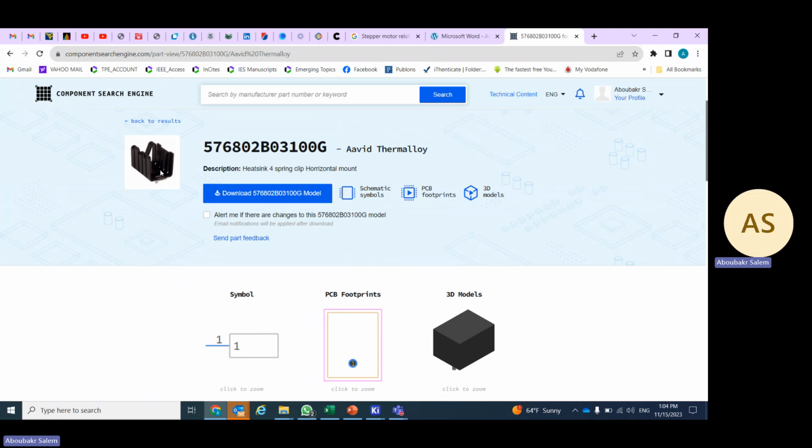In this case, we have to make our board so as to keep this heat sink lying on the board, and we will bend the regulator to a right angle, 90 degrees, after soldering, okay? Right angle in order to connect the two heat sinks, the internal heat sink of the regulator and the external heat sink. And there is a spring here in this heat sink. This is going to press all the time on the regulator to keep the heat sinks connected together.